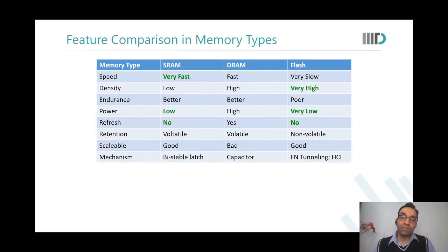Now, when we talk about these different on-chip memories and off-chip memories, on-chip memories are typically SRAMs. Whether we're talking of L1 cache, L2 cache, L3 cache, when it is on-chip, it is typically SRAMs. They are very fast, but they're not as dense. We talk about 6 transistor SRAMs. You've heard about 6T SRAM cells?